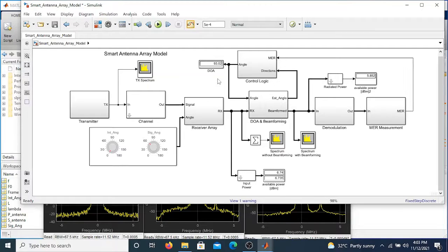So you can measure the input power and radiated power, and then obtain your efficiency from those parameters. Then, using the equations presented in the presentation, you can calculate your directivity. Finally, the gain is the product of your efficiency and the directivity, which gives you the final gain parameter.